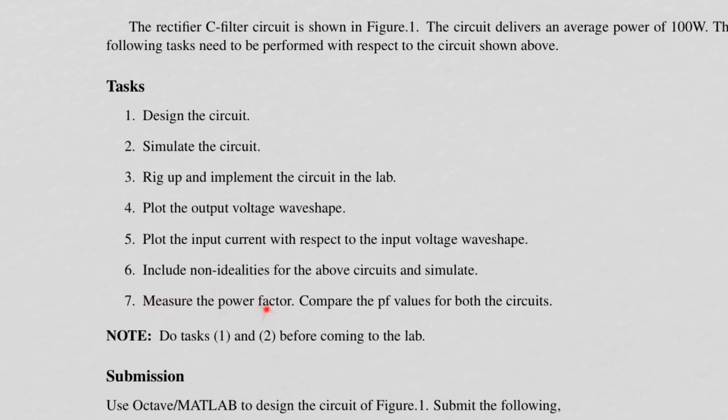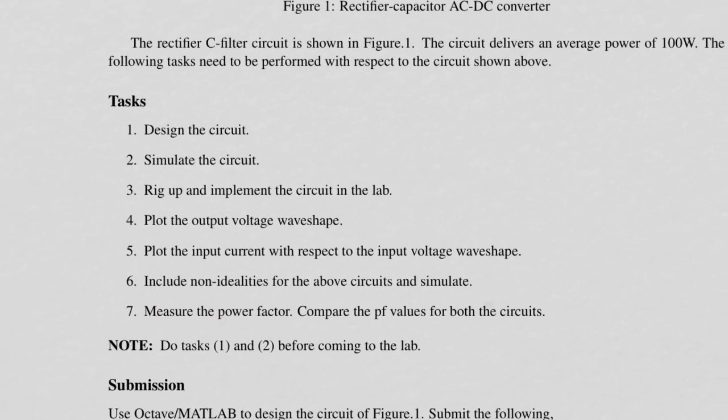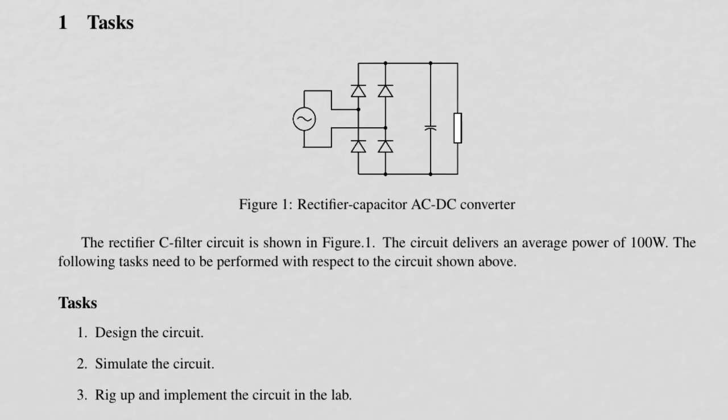The last one is very important: measurement of the power factor. Because this is a nonlinear circuit, the currents are not sinusoidal. Even though the voltage may be sinusoidal, the current drawn by the power supply is non-sinusoidal, peaky, and this is known to be a very poor power factor circuit. So that is a disadvantage of this circuit, even though it is used most popularly everywhere, basically because of its low cost, low component count, and best volumetric efficiency. The power factor is bad.